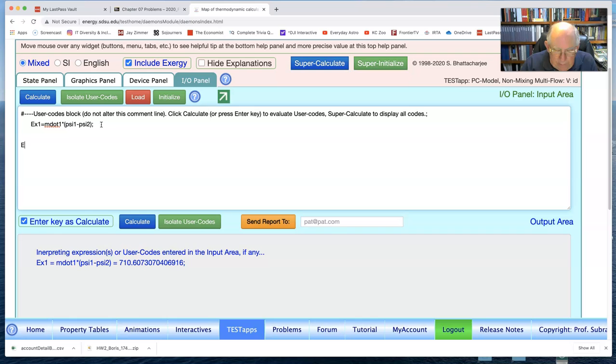And now if I calculate a second one, I call it X2, m dot 3, which is the second stream's m dot, and now I know that it's picking up exergy. In order to make this a positive number, I'm going to realize that it's going to be the higher value minus the lower value. And so we see that 446 is picked up by the other stream.